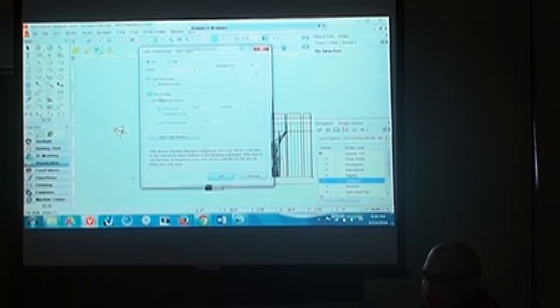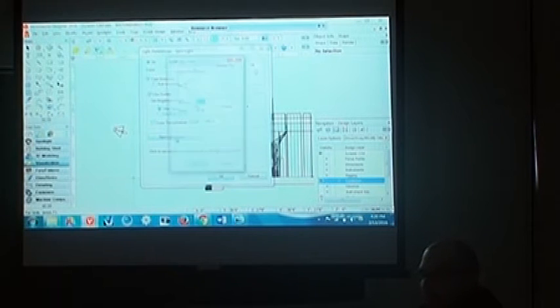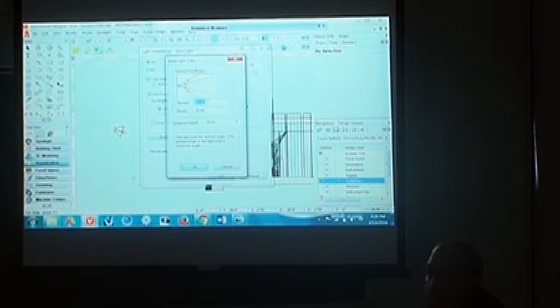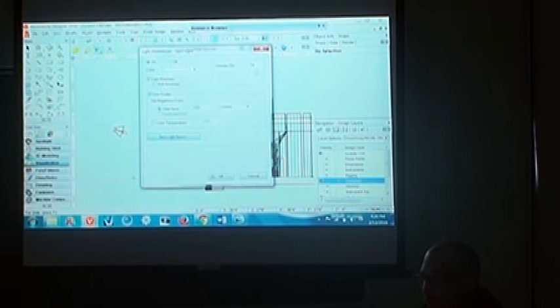I typically use the use emitter because you can set the brightness of the light source when the dimmer is at 100. So if I need to get more brightness out of that light source, I can go in and just increase its ability to go brighter. I can also set the color temperature. If you go to Spotlight Specs, you can set the beam spread for this light source. So that's all good. I'm just going to say, okay, it's on, it's at 100%.